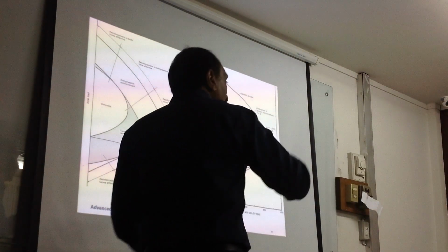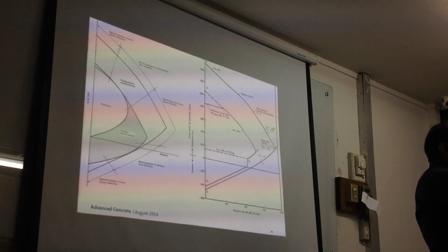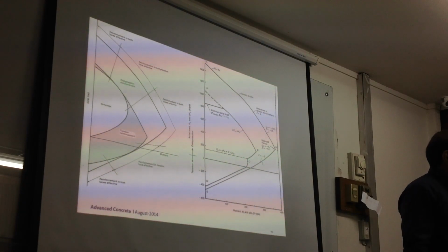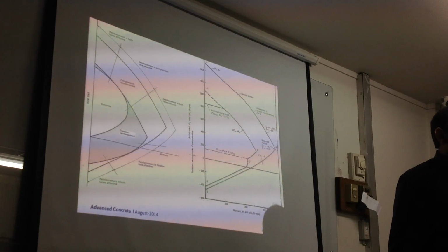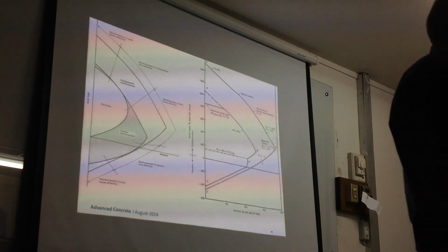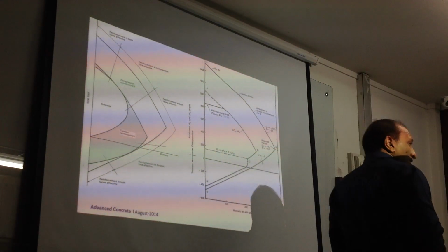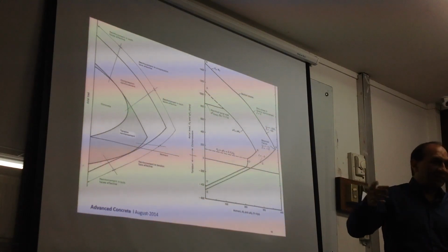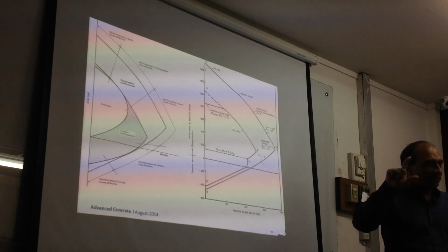Then another case is when the reinforcement on one side just reaches the yield and the other side reaches 0.003. What is that called? You must know that. Yes, balance. Balance condition is when the reinforcement has just reached the yield and the strain on the right hand side or left hand side has just reached 0.003, or whatever is the failure strain. That is the balance point, right?